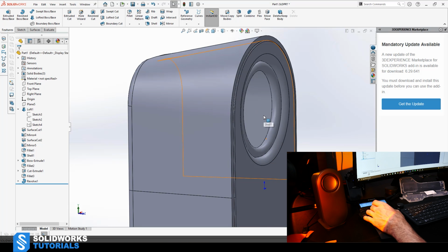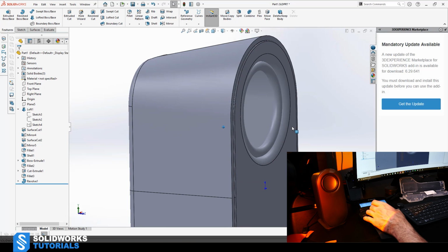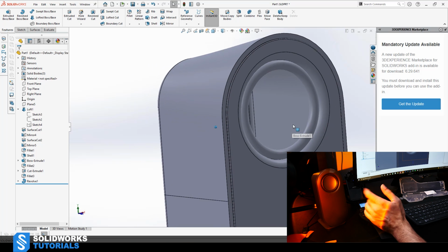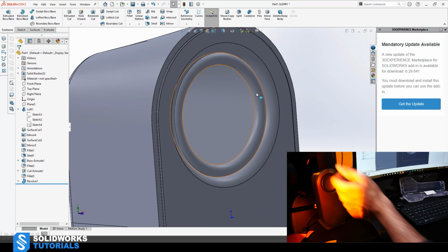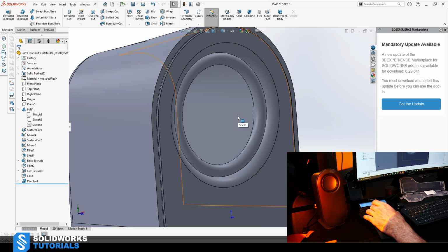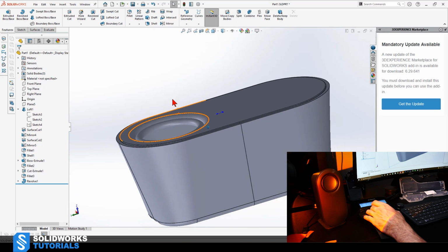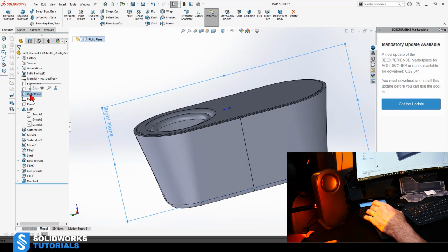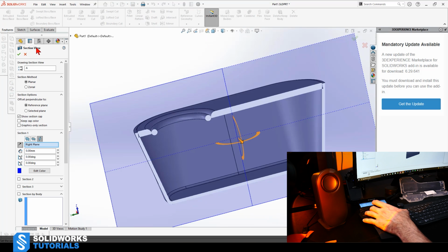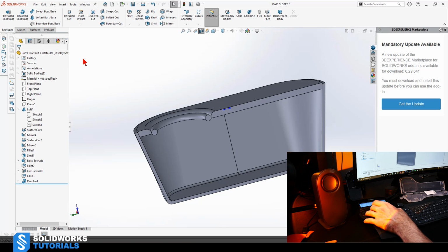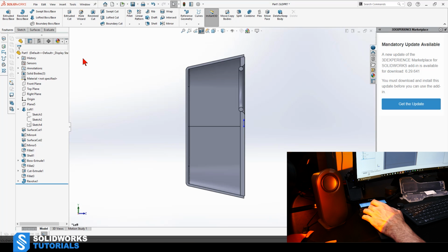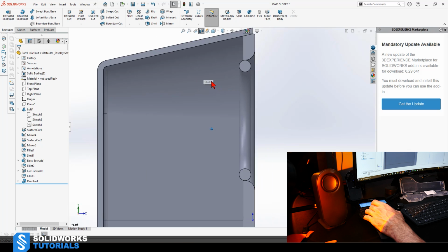Well, if it was a little bit higher and I would just draw a surface, then I would use freeform and immediately create this, which is about a couple of seconds of work. But I'm trying to make it for beginners. So again, I use right plane, cut my view in half so I can look better at what I'm doing over here. Like my view, and use right plane, activate the sketch.